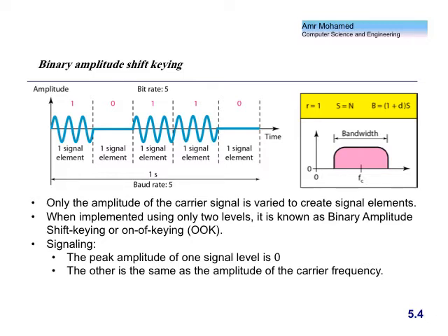So we have to give you what the D value is. Otherwise, you cannot calculate the bandwidth. And again, if D is 0, this means I'm hitting the minimum bandwidth. But in order for me to hit this minimum bandwidth, I have to have a perfect circuit and perfect filtering and modulation, which is not practical. That's why I have to push D a little bit. So D, for example, 0.5, 0.3, something like that. Okay?